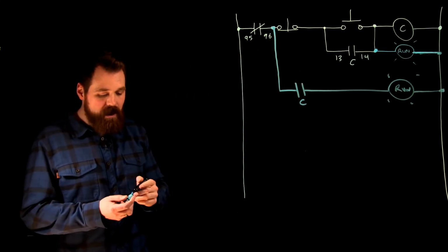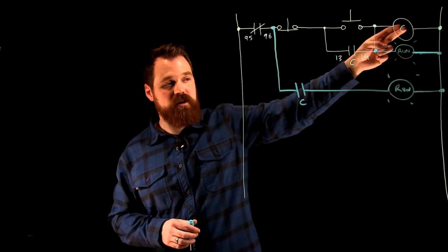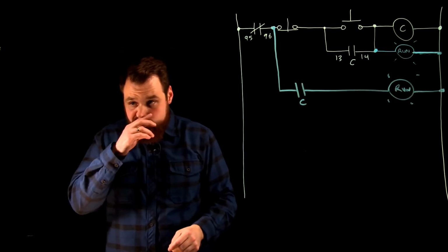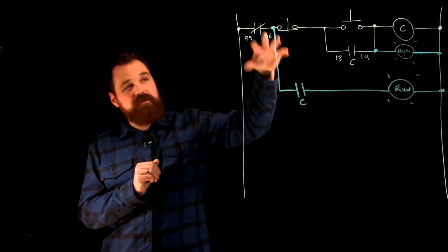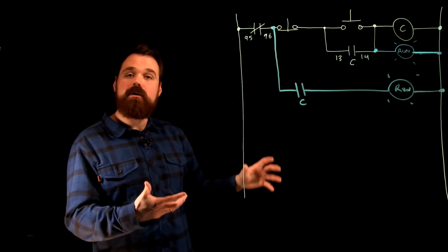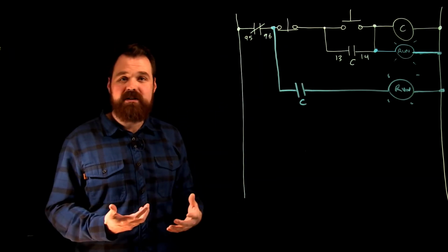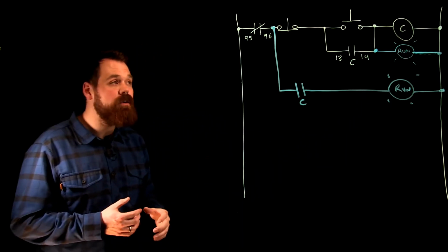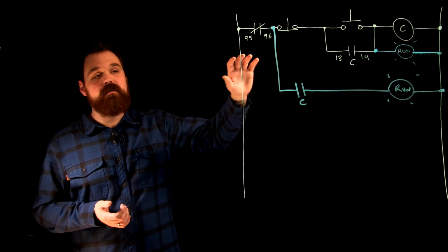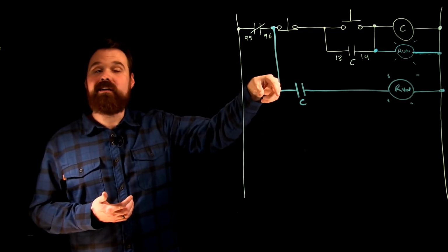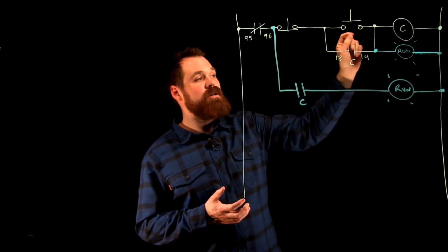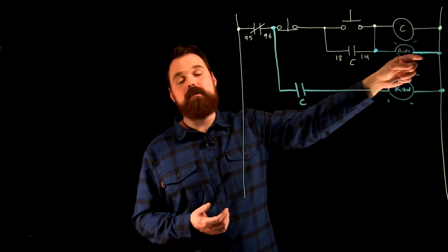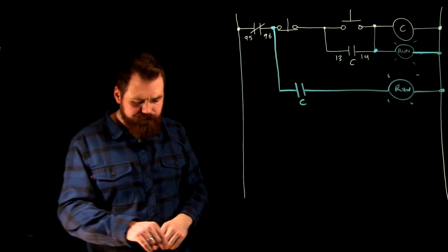And again, anytime that contactor is energized, this set of contacts would close, which would turn on that run light. And the reason we want to come after that set of overloads is just if there is an overload condition and that set of contacts opens, the run light won't be on. If you're dealing with a NEMA contactor, your overloads may not be up at the front, so you would just come right off of NEMA 1, as well as you could go still in parallel with the coil, you would just come off of NEMA 3 instead.